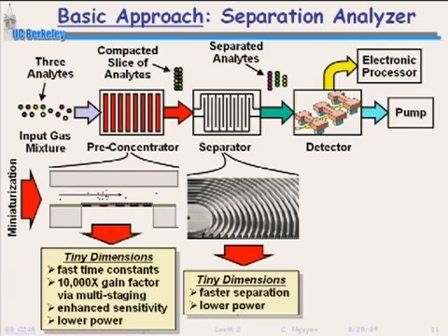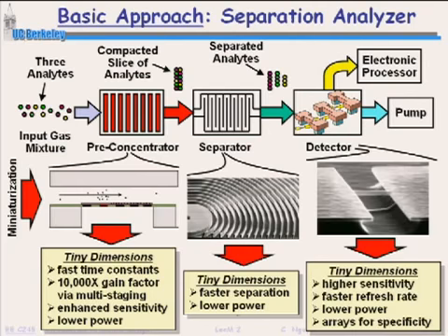But they also get much better as you shrink their sizes. Think of it: you're shrinking a beam down. You have a beam resonator like this, and you shrink it down to maybe a nanoscale like this. Now suddenly the beam is so small, its mass is tiny, its volume is shrunk enormously, while the surface-to-volume ratio went up. So the surfaces that the gases can interact with have effectively gotten bigger, while the mass of the thing has gotten smaller.